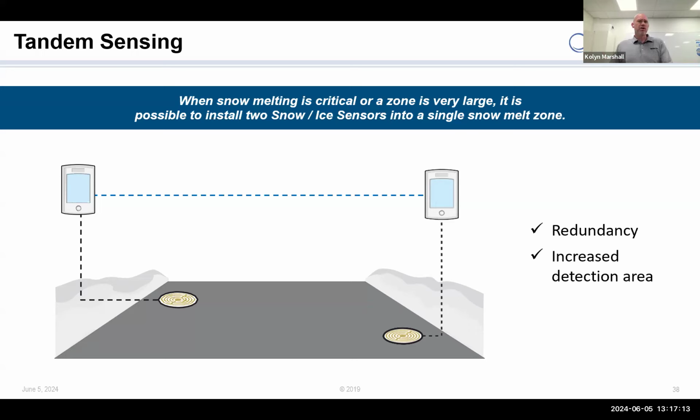If it's a really large area, you may install multiple sensors and get an averaging across the large area and not be reliant on one spot. This comes into play depending upon the shape of the area. You can have buildings that cast a shadow across an area. That shadow can impact solar gain.